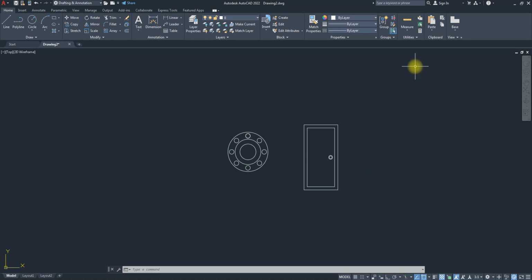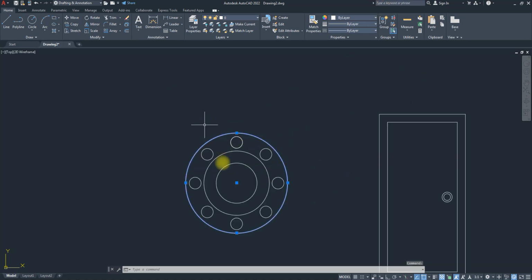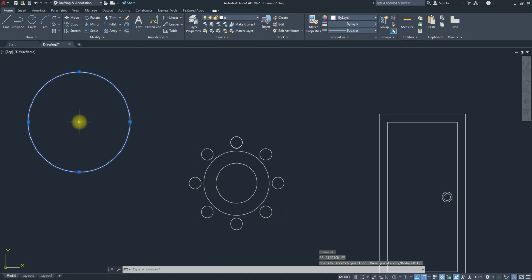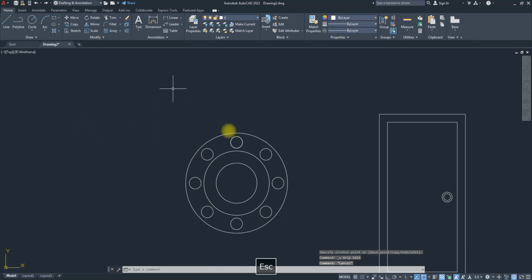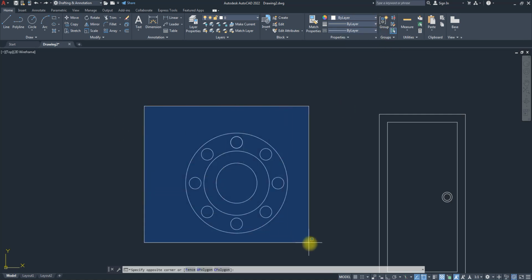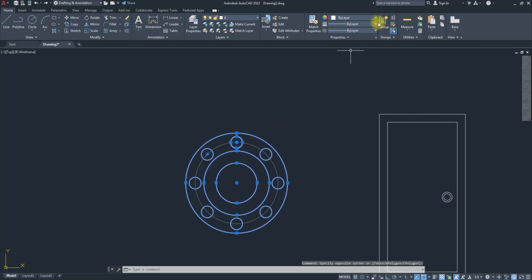I don't use it often, but it's here. So if, for instance, I have this object right now, you notice there are still individual parts. This is still one part of the object that I can move away, and the other part. So I can actually group these and make them one object. For me to group this object, I have under my group panel this icon. Yeah, I'm recording. So what I will do is first highlight what I want to group, then come up to this place and click on this group. Once I click on group, that's it. That object has been grouped.